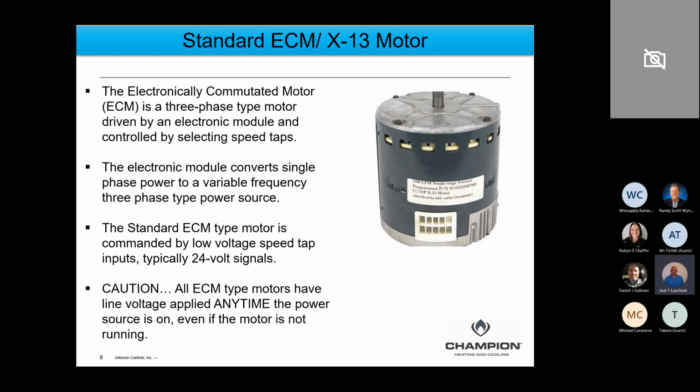Another little side note, please write this down or put this in your back pocket: if you remove an ECM motor from a blower housing, or from an air handler or a furnace, and you shut the power off, please let that motor sit at least 5 to 10 minutes, because there's a bunch of capacitors inside that module that will actually hold a voltage. A capacitor has the capability of holding a voltage, a charge, in other words.